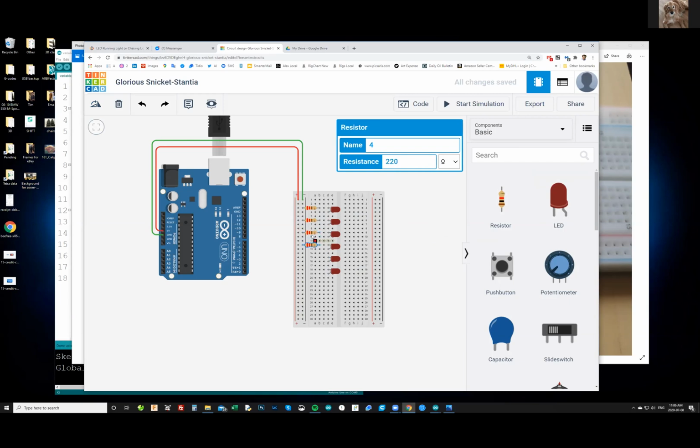So remember how yesterday we had 2 LED lights with transistors, right? Now we're adding more lights with resistors. Alex, one of my LEDs has 4 legs. Yeah, that one is multicolored. It's a common anode LED, which you can control with several pins, and it will illuminate any color you want. So you can control the shade of it. Oh, okay. But right now, for this exercise, we use the regular ones. Actually, use different colors.